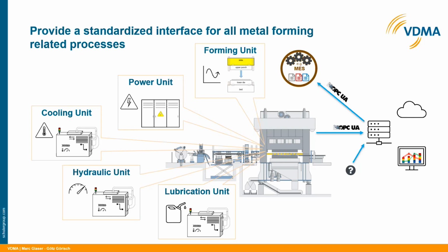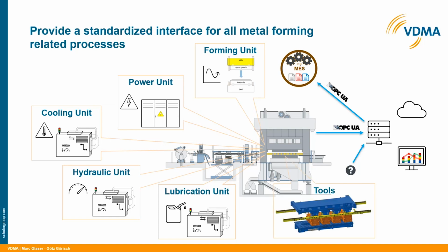And what I also want to mention is working with the tools that I've already mentioned in the introduction. What is very special in our use cases with the metal forming. On that picture below with the tools, we have the case that I also mentioned in the introduction. We have a machine with 4 stages and a 3x transfer. So those 4 stages are all inside one machine, and with each stroke, or each cycle, or as we say in the specification, each run, we put the part to the next stage with the transfer. So the flow direction is normally from left to right, and then we have a ready formed part at the end on the right side of the image.